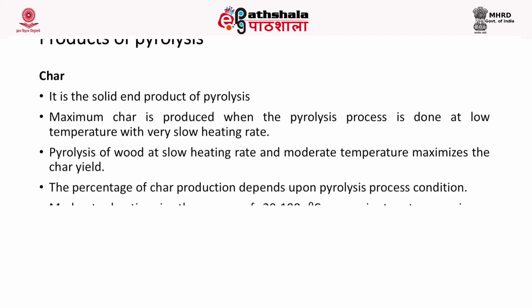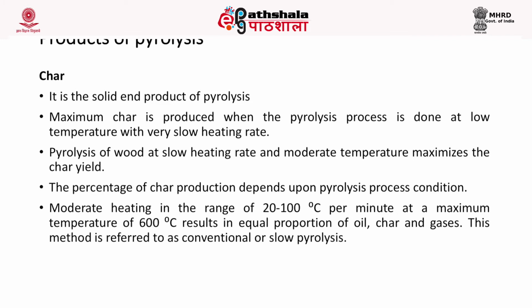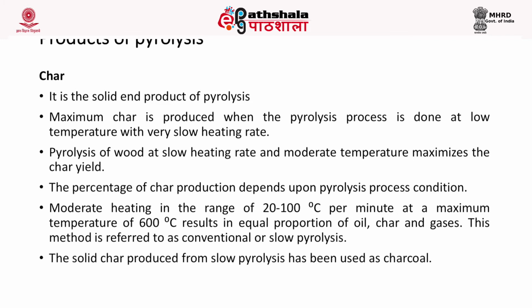First, let's discuss char. Char is a solid end product, and the maximum char is produced when the pyrolysis process is done at low temperature with a very slow heating rate. Pyrolysis of wood at slow heating rate and moderate temperature maximizes the char yield. The percentage of char production depends upon pyrolysis process conditions.